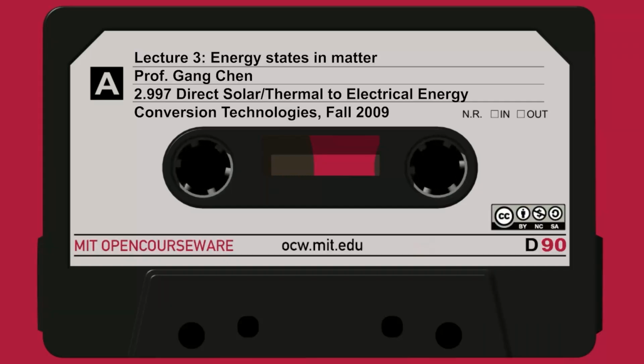If we do the device analysis and find the efficiency or the coefficient of performance, we find that those depend eventually on the material property, which we call the figure of merit ZT. And of course, those are heat engines, so the pre-factor is a Carnot factor times something that's less than 1. And this less than 1 depends on the material property. And ZT, we want it to be as large as possible.